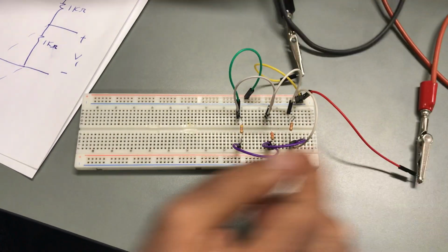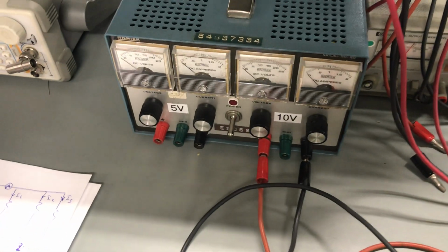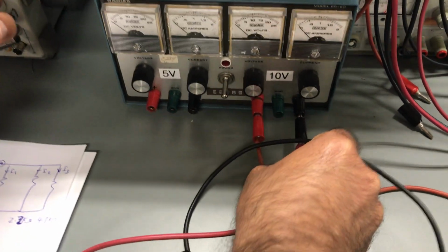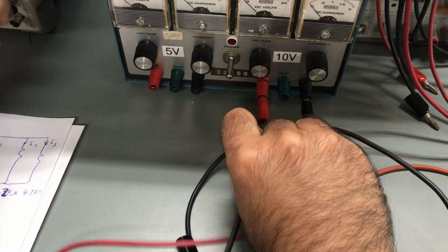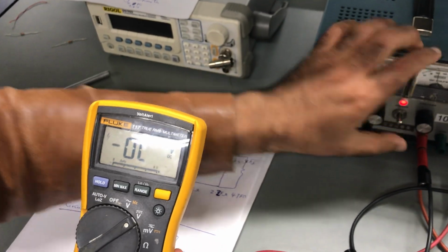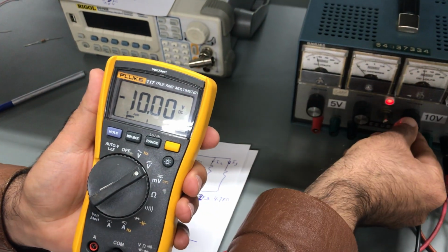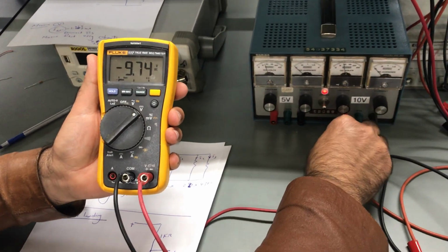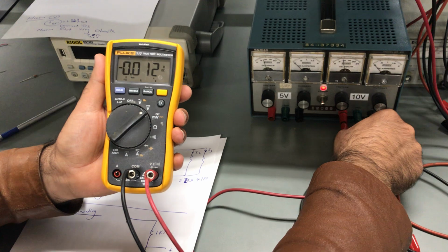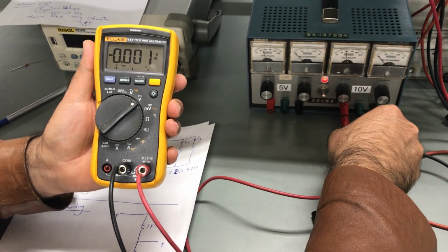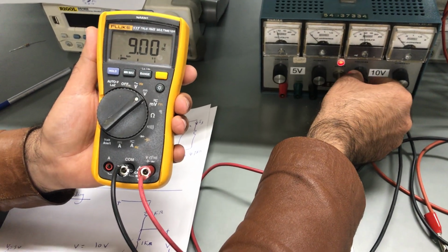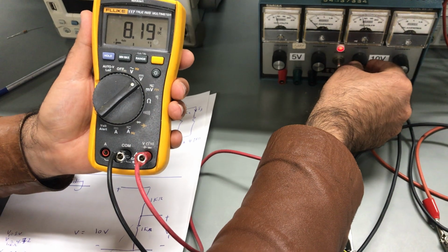So now this is my power supply. I will adjust it to 6 volts. I will use the voltmeter to adjust the power supply for 6 volts. So turn it on, and then I will reduce the value of the voltage. Oh, I'm connecting in the wrong direction, so I will switch positive to positive and negative to negative. So I will change the value till I reach 6.